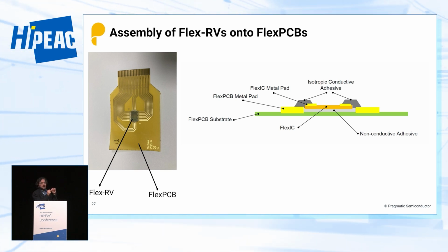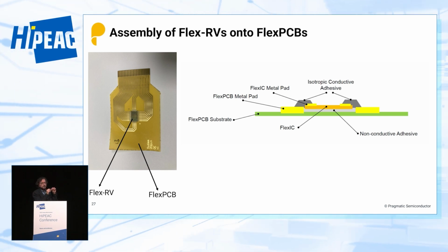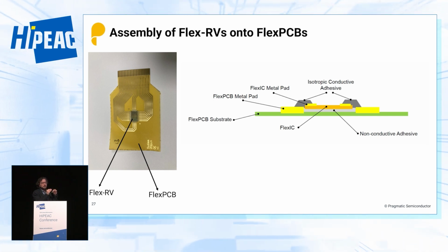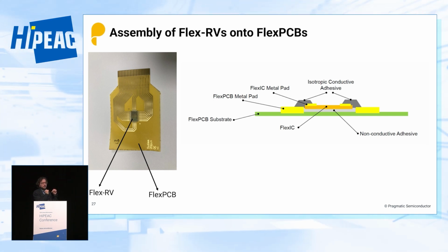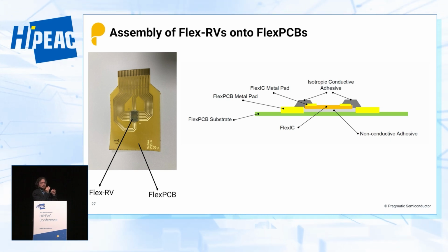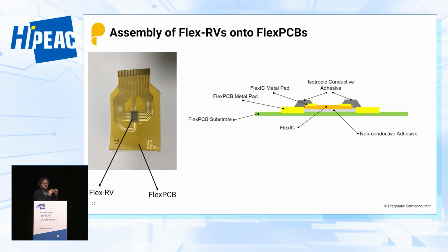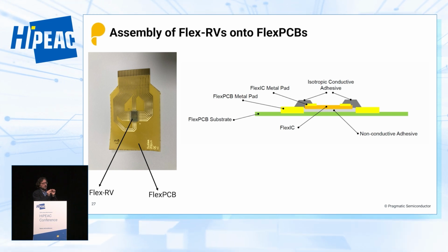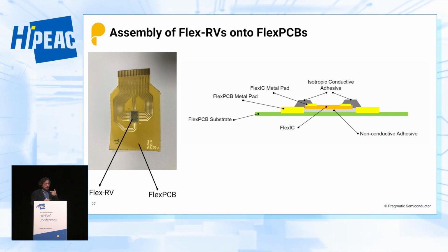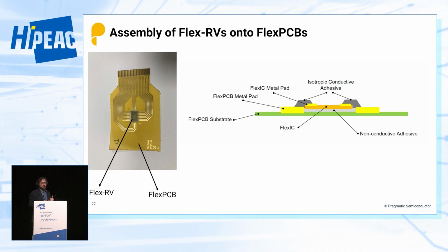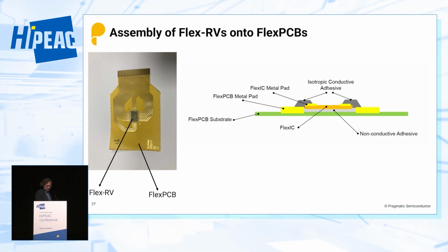The pads are aligned, so there are metal pads on the PCB. We use inkjet printing to connect the pad on the die to the pad on the PCB. There's also some adhesive in that ink, so it connects together. So you can actually bond. You don't need to do extra packaging in the sequence. That's also another factor to reduce the cost. So there's no special packaging required.